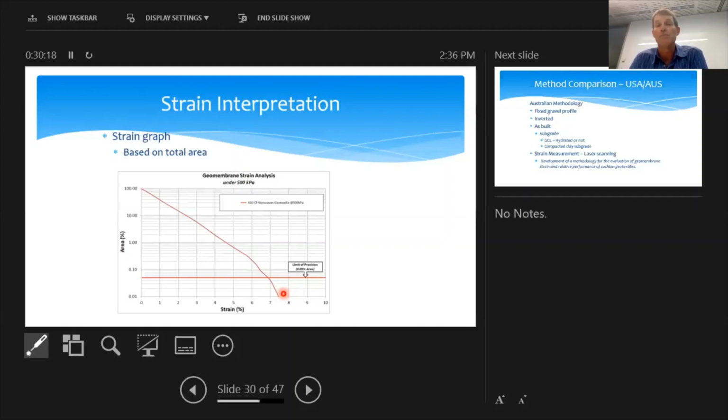So we stuck with the 1 millimeter grid, not because of any scientific reason other than that the computing time to do the analysis was going to take too long. These days, with computer technology moving on, we probably could reduce it to 0.5 millimeter squares and do it at the same sort of price, but that's just the way we started the testing, at 1 millimeter squares.